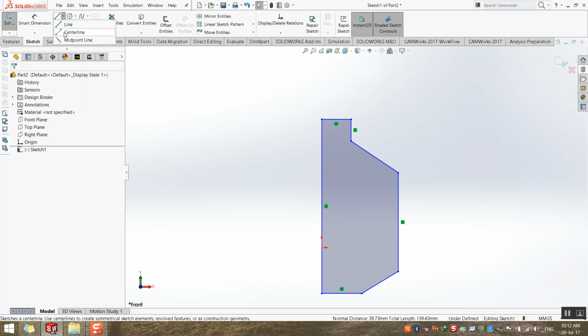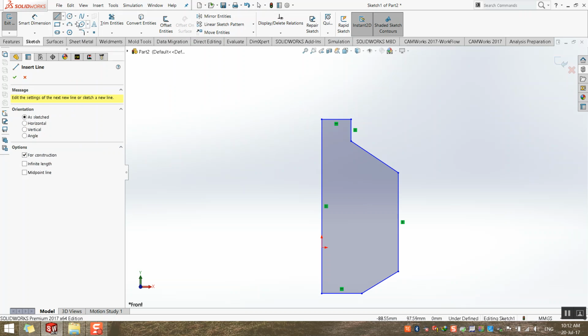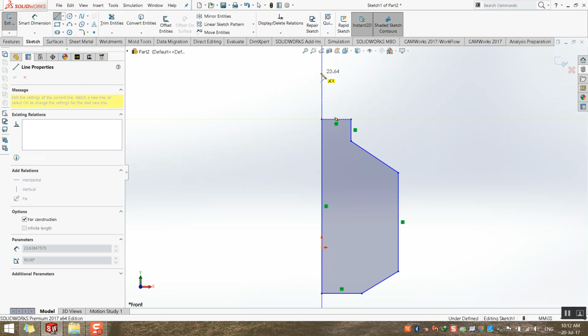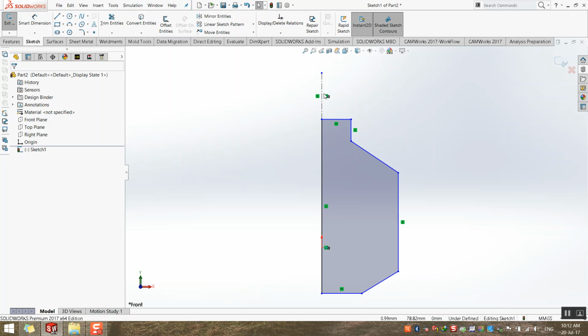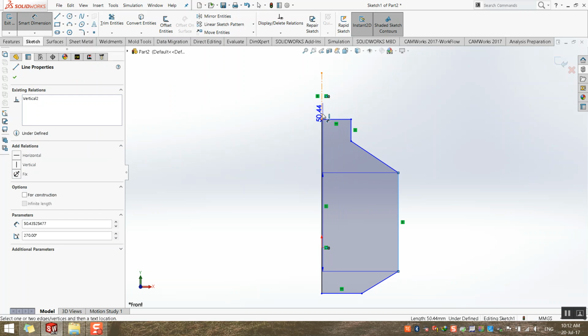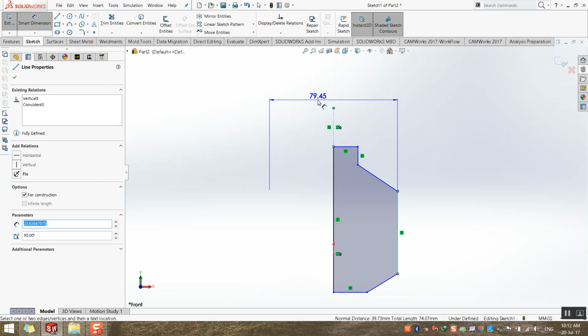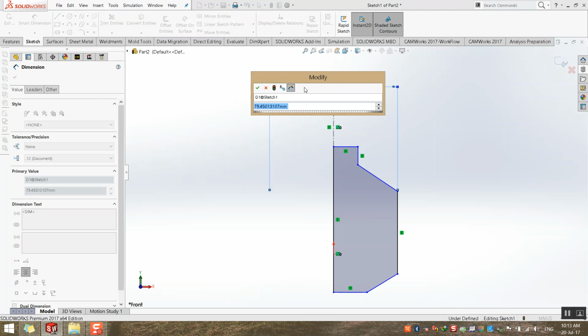You can do that with a center line. Do you remember center line? Yes. When you do this center line and get smart dimension between this edge and the center line, automatically, because it will think that you now need a diameter, you will do revolve, okay? Automatically the really smart dimension has been converted to diameter.